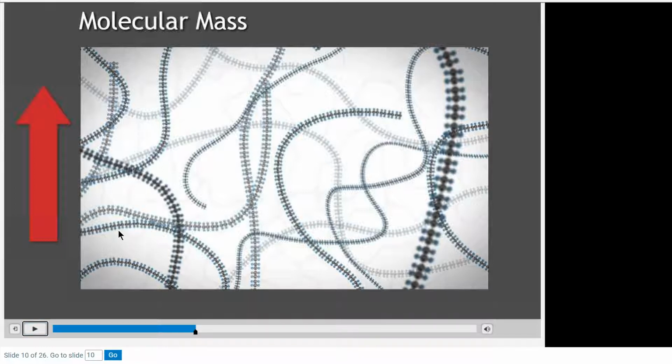So every thermoplastic material has reoccurring molecules. And they build a chain, and the longer the chain is, the more entanglement, the more difficult it is to heat up, the more difficult it is to align those molecules like spaghetti to be able to inject them into a mold. Okay, that's very, very important. Understanding this polymer material can help you solve processing questions.